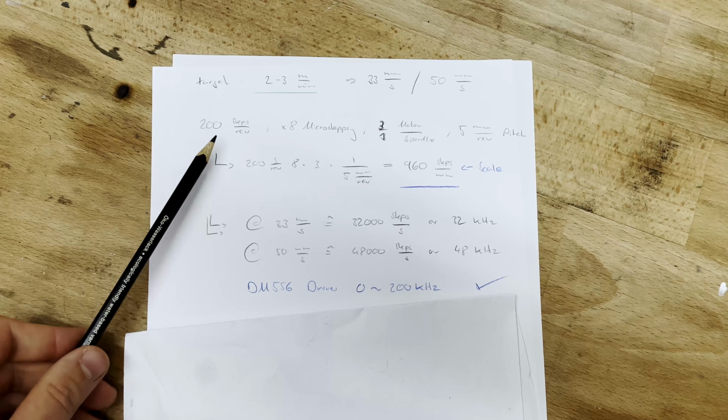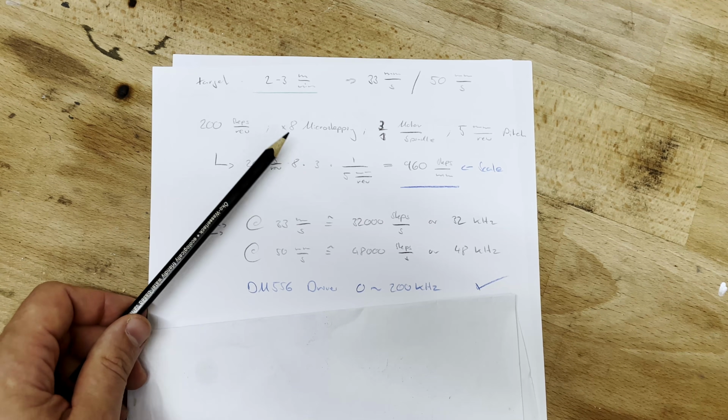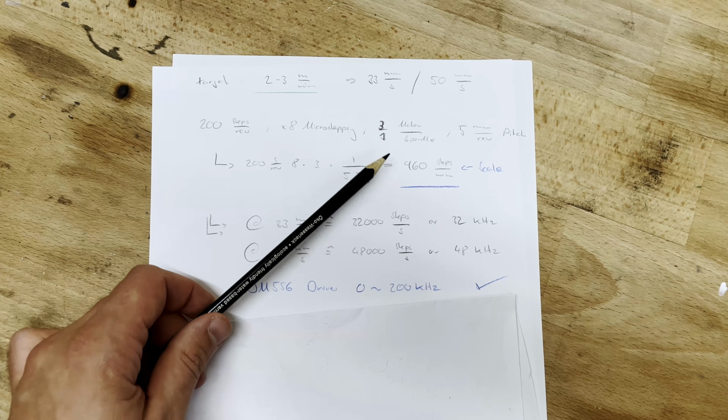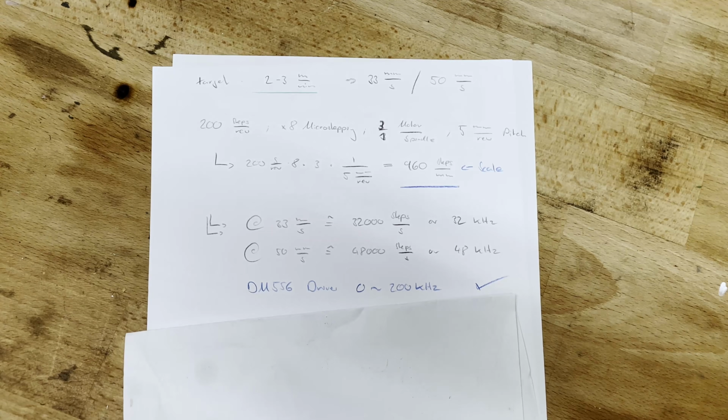On my setup with a 1.8 degree stepper, an 8x microstepping setting, as well as a 3-to-1 reduction between the motor and the lead screw, which also has a 5 mm pitch, I get 960 steps per millimeter, which is also the scale that I put in the ini file.